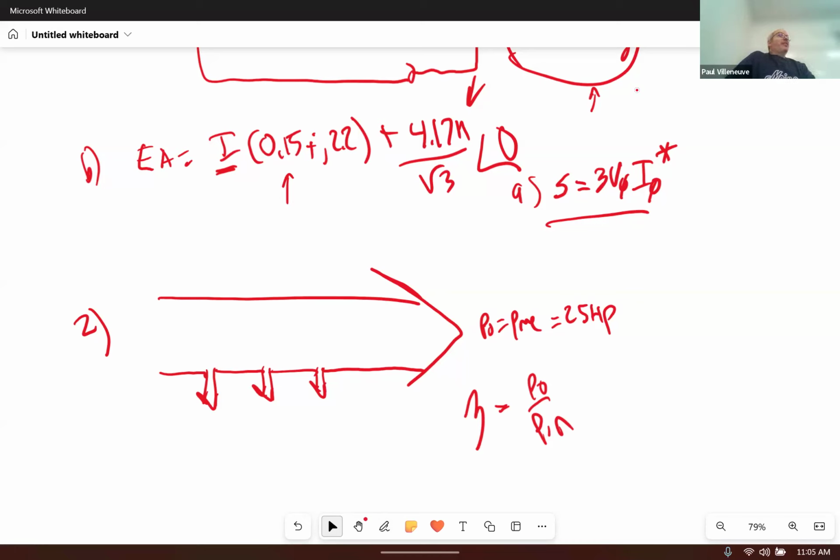So this had actually nothing to do with synchronous motor generators. This just had to do with power equations. This is going back to your introduction to circuits, right? When you were taught efficiency. So to solve for problem number one, we didn't even need to know if it was a synchronous. I could have called it a box and said the box has an output equivalent power, 25 horsepower, and the input power is it's 92% or 82% efficient. You're going to be able to calculate that out.